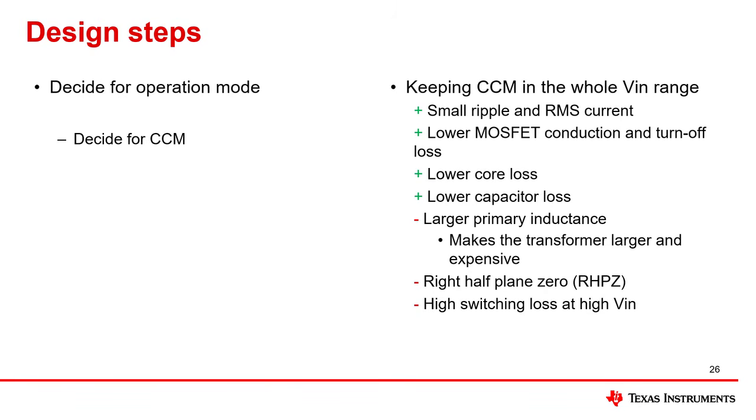The first step is to decide on an operation mode. As explained before, both operation modes, CCM and DCM, have advantages and disadvantages. In this example, we decide on CCM operation mode over the whole input voltage range.